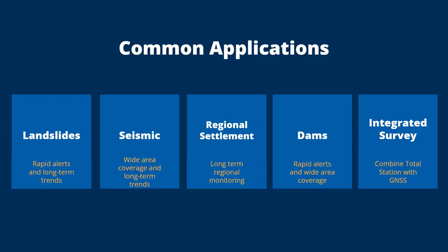And then we have updated locations of those monitoring prisms. So every time we run that resection, even though those antennas and prisms are moving, we're getting new locations for them. So we can more accurately and reliably run that resection and get a realistic representation of what's happening with our prisms based off of that GNSS correction.